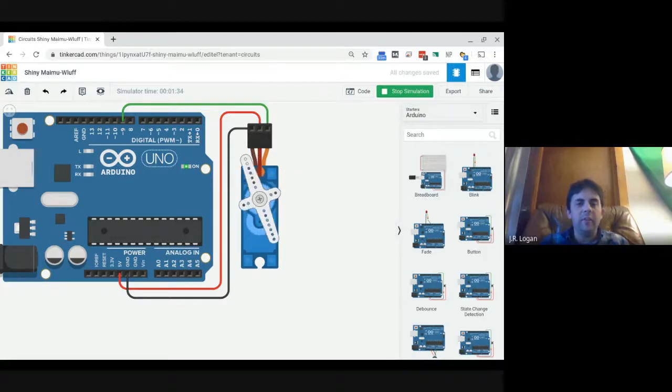And so that transistor will be able to turn on and off the higher voltage signal, which can run your motor and is appropriately set up for your motor. But it will be using the lower voltage signal that comes from the Arduino. And so I think it's a good time to let Lurch give me his impressions, thoughts and questions, because I've taken you as far as my competence allows. So Lurch, what are you thinking?